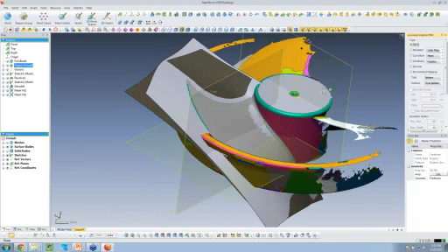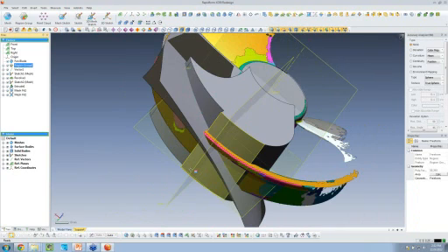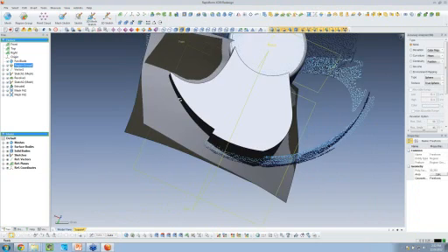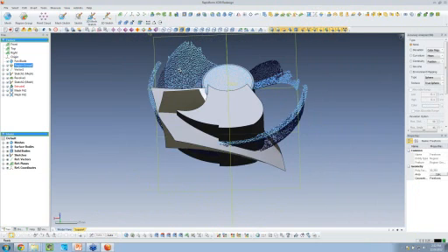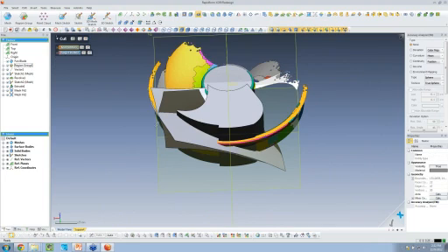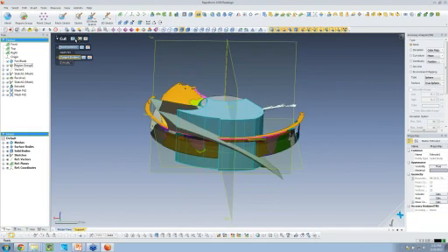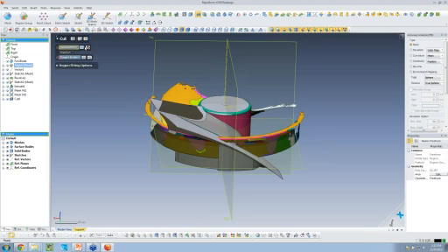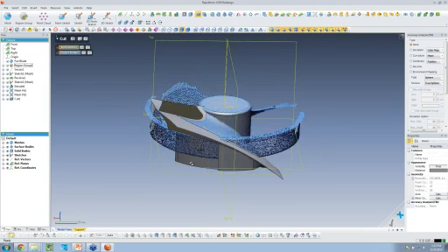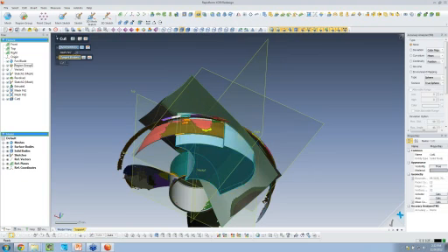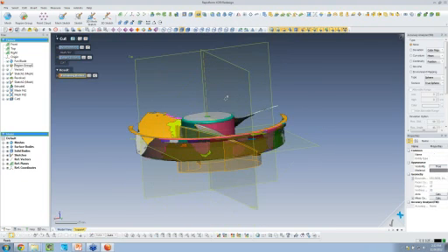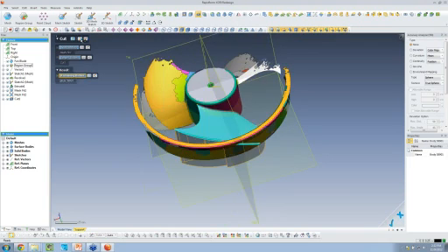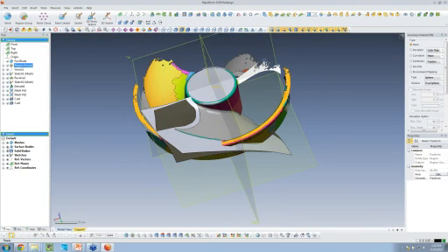So we have these two surfaces. We have this nice solid body that we created that hopefully goes through both of those. And now we can use the cut command to cut our large solid bodies. The first thing we want to do is select a tool body. We want to select the solid that we used to create that, and we want to highlight what we want to save. What part do we want to keep? So let's do that same thing once again. The target body, and this time when I select, now I need to select that real small margin, the smaller part, and there I have my solid bodies now.